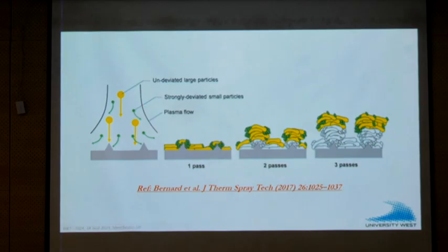So what is critical, based on what knowledge is available in literature, is that if very fine powders exist from a suspension, they don't travel straight, they travel like that. They go with the plasma drag line and then they deposit on these asperities or roughness, and then slowly that builds to form a column, right? So that is known. So that tells me that as long as you get these fine particles, it doesn't matter how you get them, correct? As long as you get fine particles, you should form columns, right? That's my hypothesis, whether right or wrong.